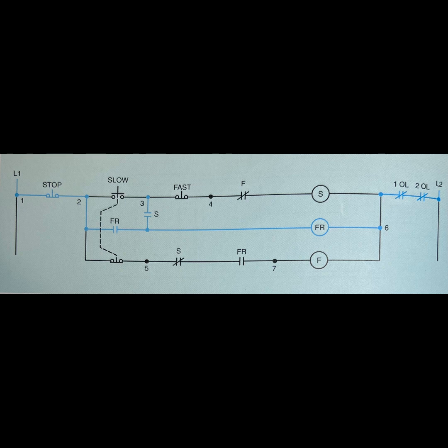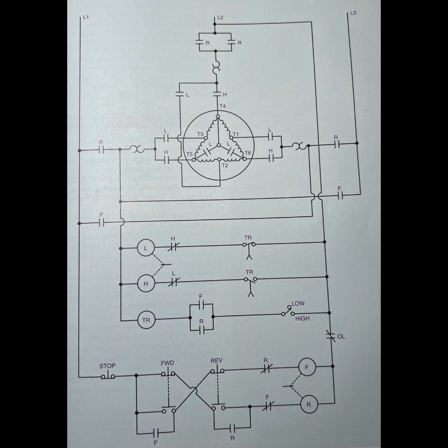The upper oil inspection plugs, also called pressure plugs, in large gear reduction boxes should be removed while testing the machinery. Failure to remove these plugs may create broken casings in the motor if the motor is reversed accidentally. Machines can be damaged if the directional rotations change from that for which they are designed. In general, the correct rotational direction is indicated by arrows on the driven machinery or in the back.